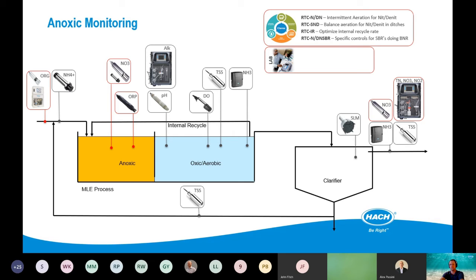So rounding out the conversation, we're looking on the right here again. We have a nitrate probe if the wet chemistry analyzer is not needed. And then at the far left, the influent, when we're talking about loading coming into a treatment plant, it may be good for us to really understand changing conditions as it relates to organics, biodetector, and or probe for total organic nitrogen or SAC. And then again, just to finish it out, the laboratory data is available on a DR3900.